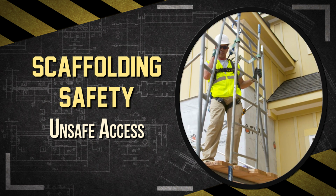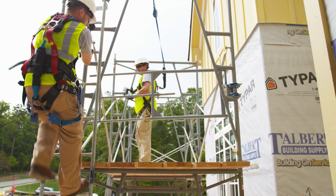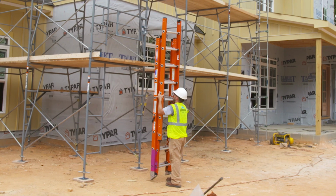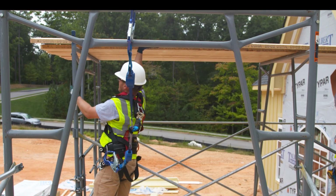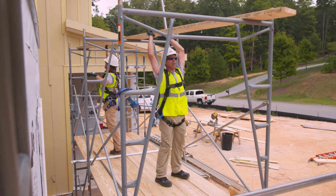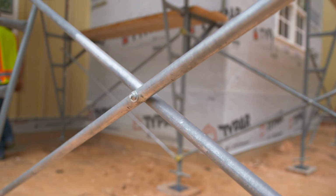Falls from scaffolds generally occur when personnel are climbing or descending the scaffold. In many cases, injuries occur when climbing the braces or scaffold frame that was not designed to climb. Safe access to the scaffold work area is required when the elevation change is more than 2 feet. Equipment that can be used for safe access could include secured ladders, clamp-on ladders, and built-in ladders. You can directly access scaffolding from another scaffold or structure, provided it is not more than 14 inches horizontally and 24 inches vertically from the other surface. Cross braces cannot be used to climb on or off the scaffold.